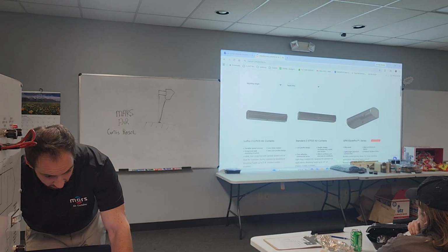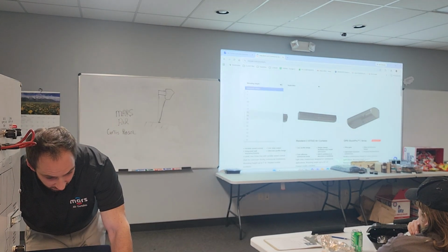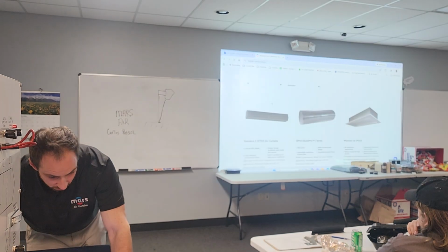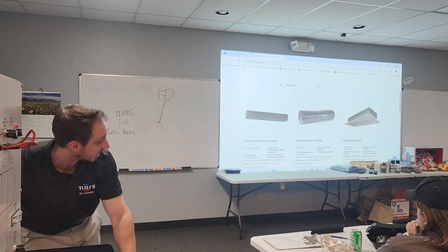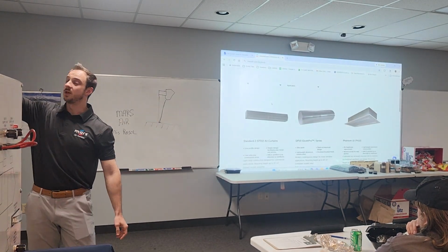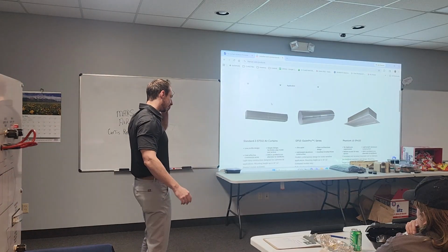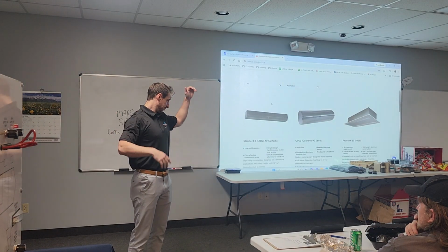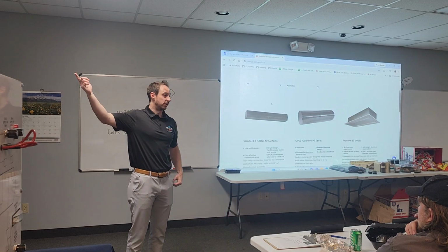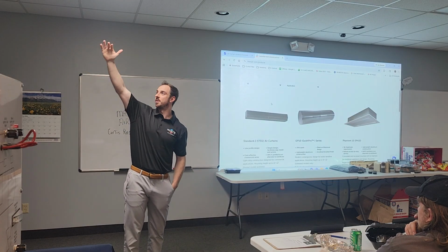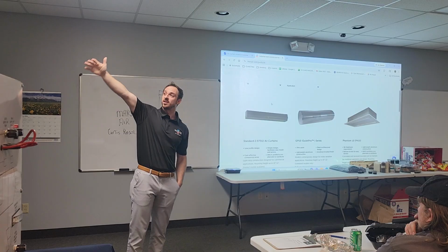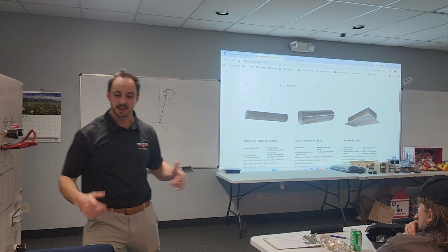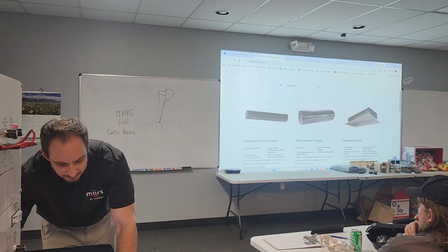Our air curtain selector tool is very straightforward. It's two questions: mounting height and application. Let's say you've got a 10-foot door opening. Again, this is mounting height. By habit I say door opening height, but I should be more specific. If you couldn't install it right above the door, and had to put it at 12 feet for a 10-foot door, you would have to select it for 12 feet. So it's technically the mounting height, but ideally that would be the door height.